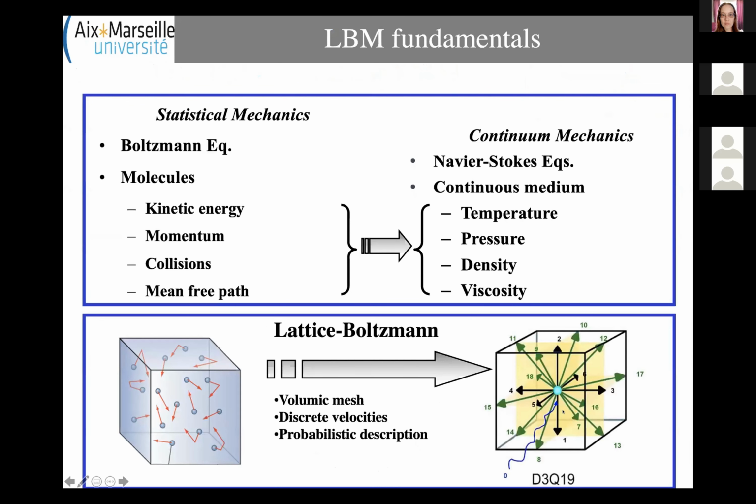I am not, of course, going to give a lecture about basics or fundamentals of Boltzmann methods. Just to remind you that instead of looking at fluid dynamics, solving continuum mechanics equations, like the Navier-Stokes equations that are based on macroscopic quantities such as temperature, pressure, density, viscosity, and fluid velocity, we are now working with the Boltzmann equation, which is based on a statistical description of the fluid dynamics at an upper level, which is the particle level.